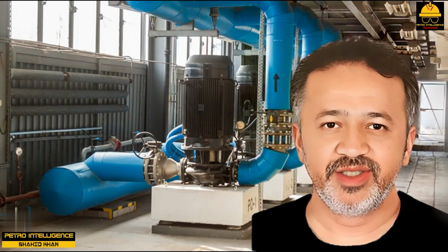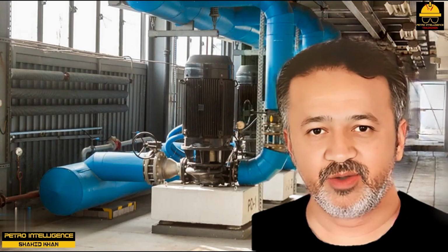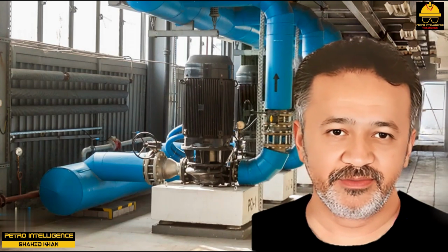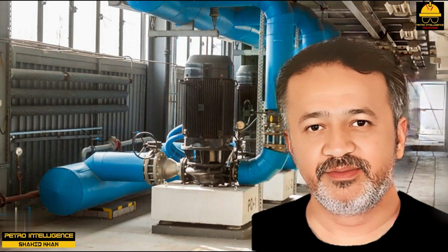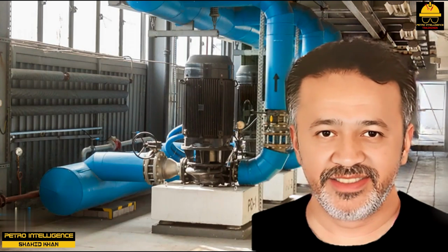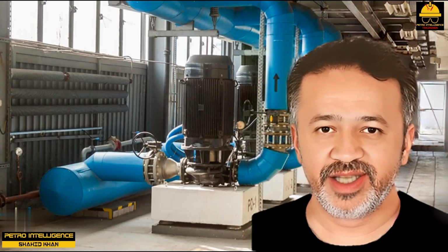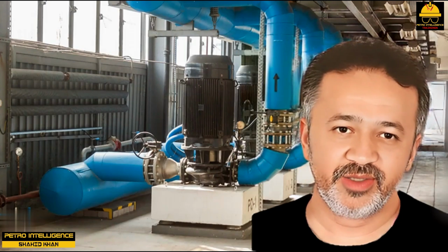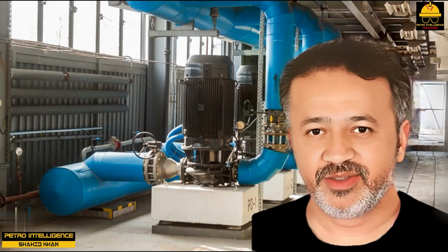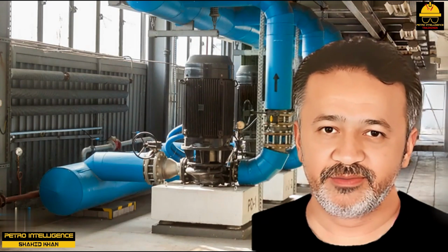But the lower required feet of head permits the pump to operate further out on its performance curve. This produces more volumetric, GPM, flow. It also requires more work to pump the greater flow. So, we have to have sufficient excess amperage on the motor driver to accommodate this maneuver. But that is the price we pay for expanding the pump's capacity without increasing the impeller diameter. Of course, the larger diameter impeller would also require more motor amperage.